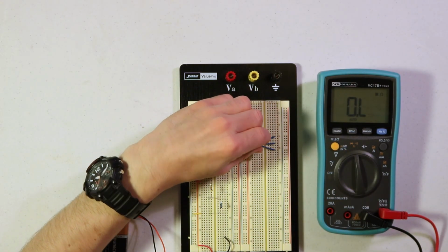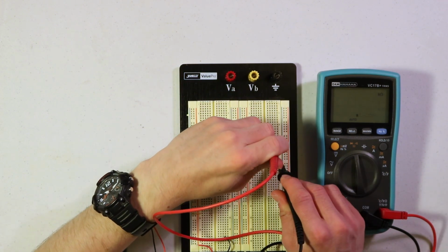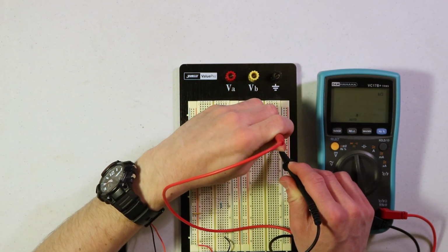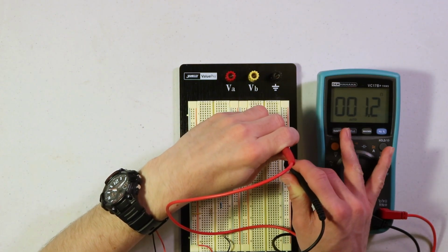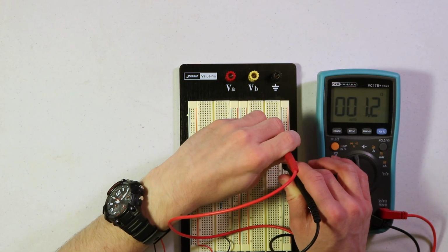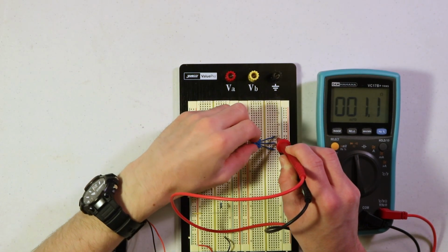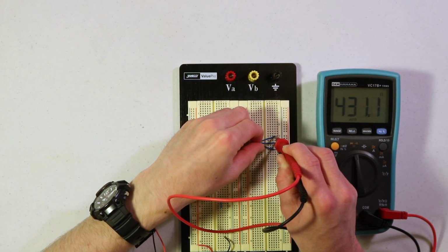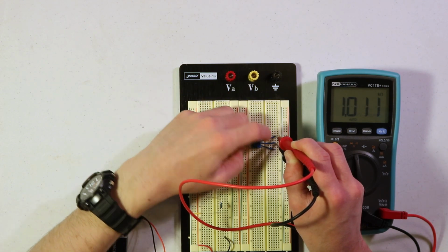Now, if we turn the knob all the way to the other side, now we should see all the resistance across pins 2 and 3, and none of the resistance across pins 1 and 2. And that's pretty much exactly what we're seeing. There's a little bit of resistance in there, but it's very close to 0. And if we just watch that, I'm going to keep these probes on here, as we turn the knob, now we have more of the resistance getting to this side, and I can keep going, and when it reaches all the way to the other side, now we have the full 1 kilo ohm between pins 1 and 2.